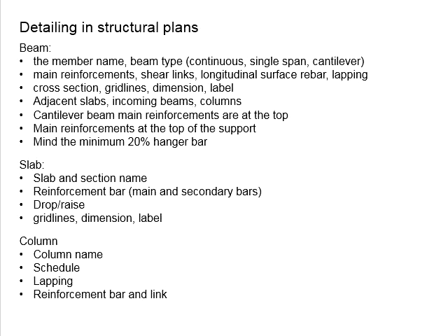You need to show the locations of the stiffener, where we know there will be a point load acting onto the beam. And some engineers also provide indications of the locations of the staircase. How is the staircase connected to the beam?